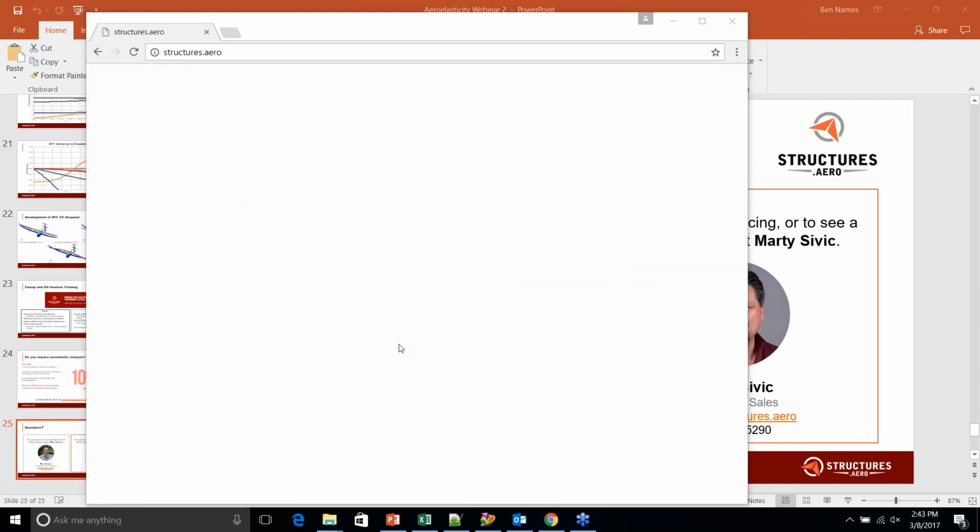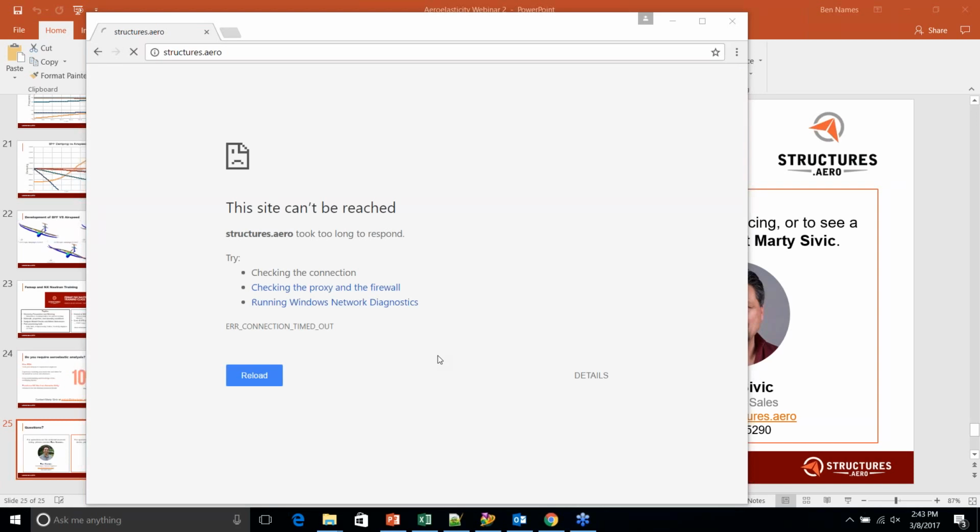In which unit will Femap follow the imported geometry? Okay, it looks like Ashwin already answered that. Femap and Nastran are unit neutral, so you do need to track your own units. That's why, for example, I was dividing by 1G in inches in the inch-based unit, because although I had pounds represented in the model for the mass, we needed to convert it to an actual true mass.